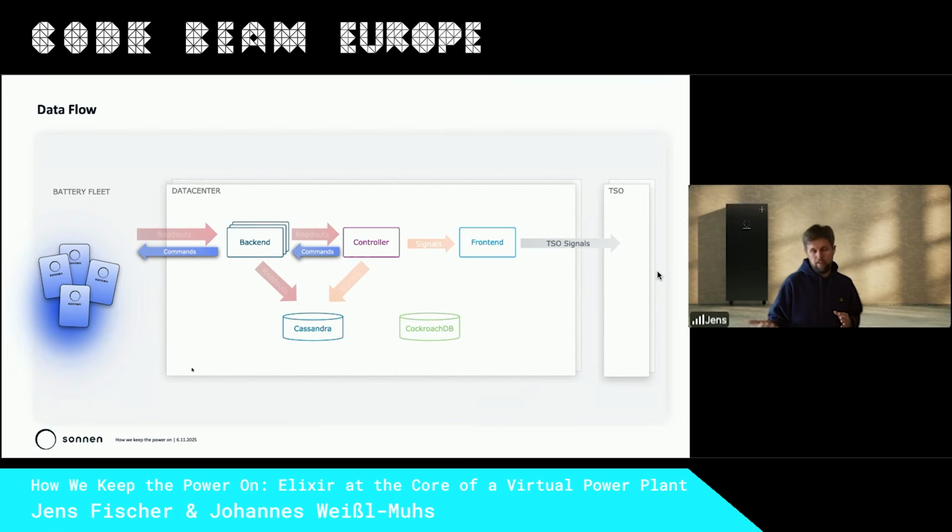So once the locally measured frequency hits one of the frequency bounds of this individual battery, then the battery starts to charge from, or discharge into, the grid to stabilize it. And together, all the hundreds and thousands of batteries, all these tiny reactions make up the whole response that we saw in the graph from the web interface Johannes was showing earlier.